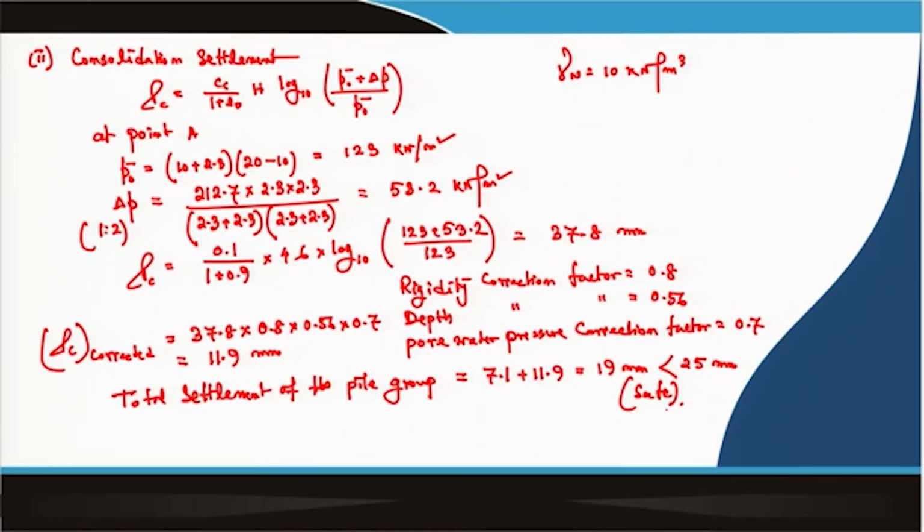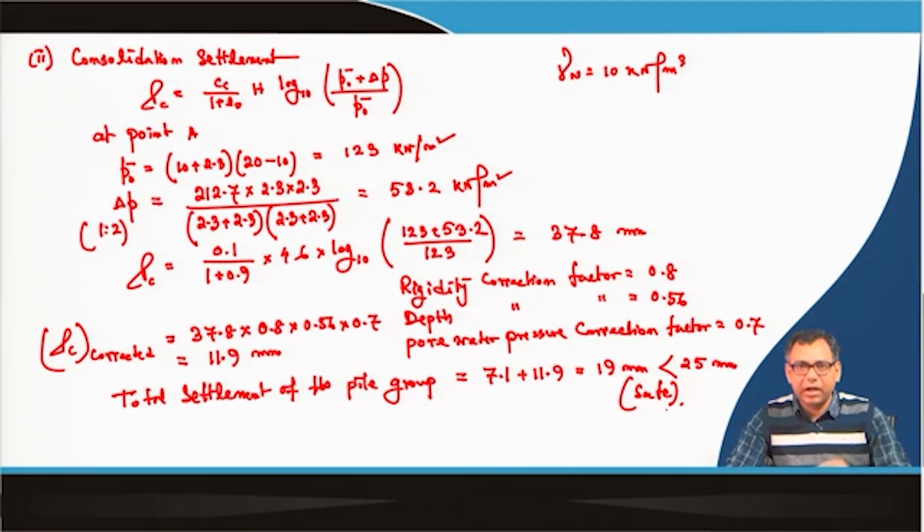So, that I have done for the clay. In a similar way, by using the pile bearing capacity equations for sand, you can determine the bearing capacity of the pile group in sand and the settlement of the pile group in sand also. I have already discussed the settlement of a raft or shallow foundation resting on sandy soil, so the same equations you can use, because I have used a similar type of equation here for settlement calculation of the pile group or the raft for clay.